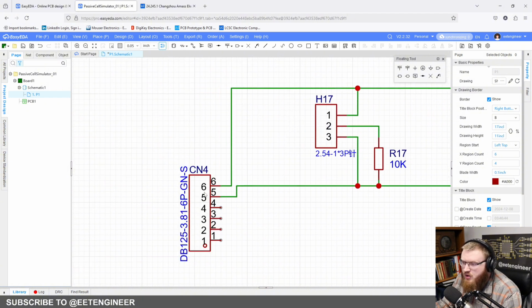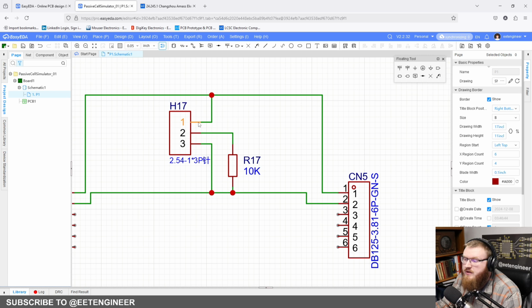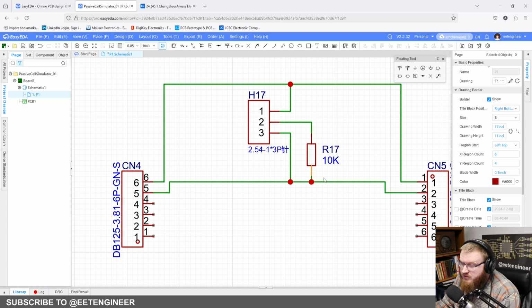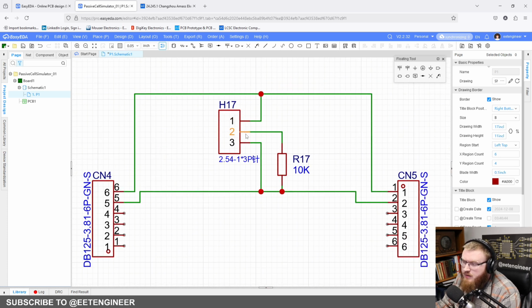thermistor. And so if you don't want to use an external thermistor, you can put a header jumper here to short across your pair here, your thermistor plus and your thermistor minus. But if you do not want to use this resistor and you want to use the output, then you can put it here between 2 and 3, which is just shorting this 10K resistor back to itself connected to the thermistor minus here. So you can use the external thermistor.